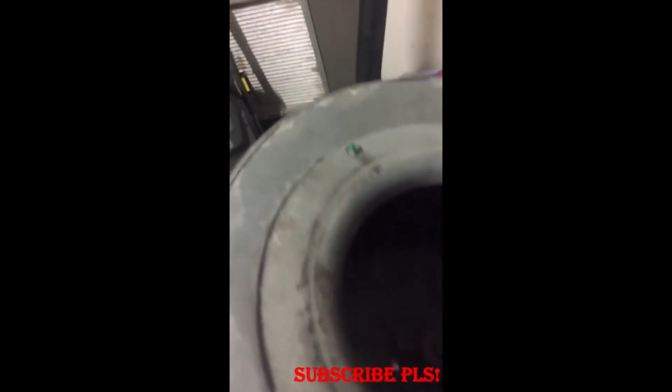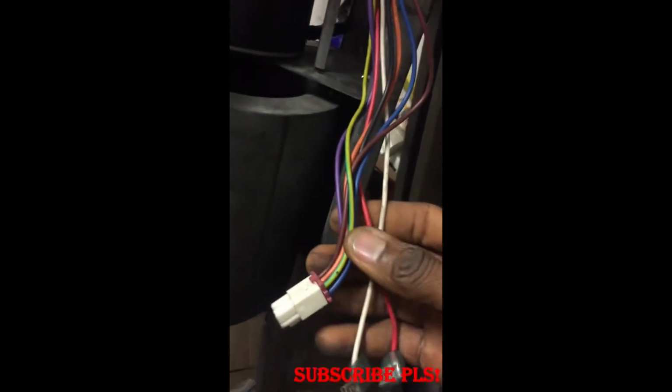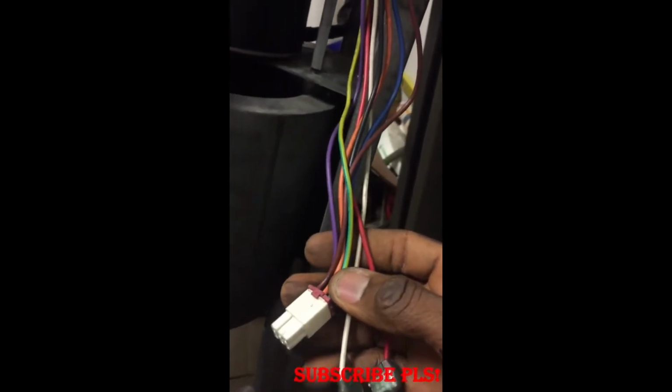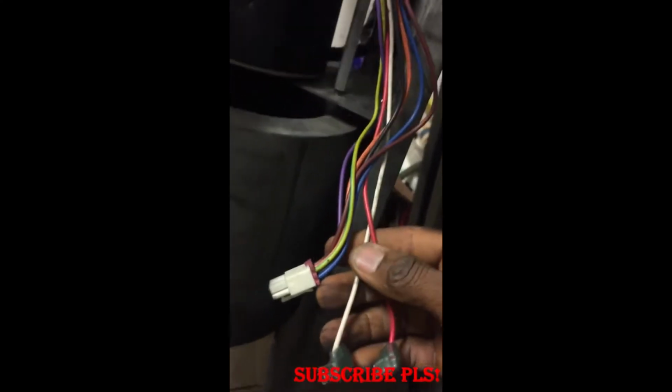This is the front part of the fan coil unit, as you can see. So all this will be useless without the fan motor that is here. If you find yourself confronted by this sort of challenge, my work here is to show you how you can identify the cables, which are the speed cables and the supply cables that are